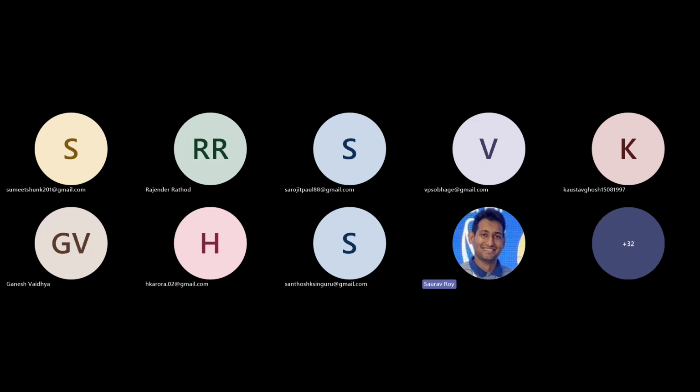Generally, you can take a small amount of length, like lambda by 10 or lambda by 5, whatever. That won't matter much. If you take a very short length, in the hardware it might affect because of discontinuities or changes in the SMA connector. Otherwise, in your simulation, it will not matter much. Okay, thank you.